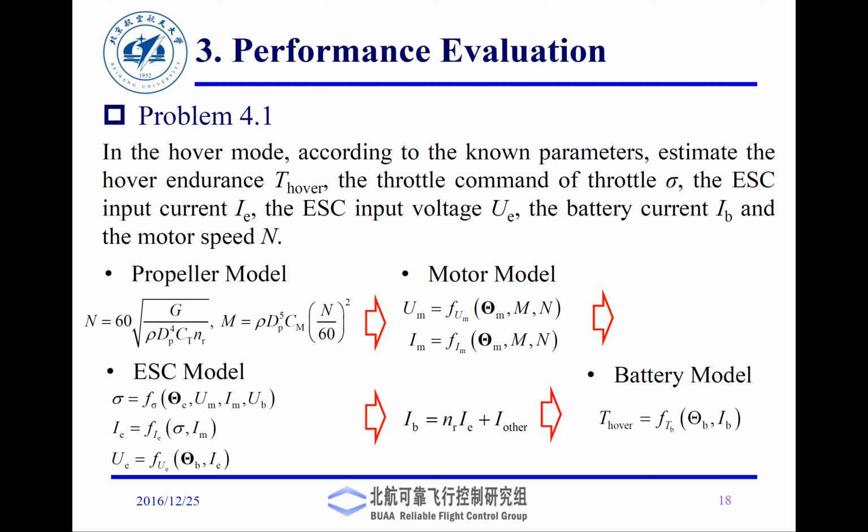It's never done at 100% throttle. You do not want 100% throttle when the UAV is just hovering. You want it to go from point A to point B. Usually, the stable hover is done at 50%. So you choose 50% throttle, work out these equations, and then find out the capacity, whatever components that you need.